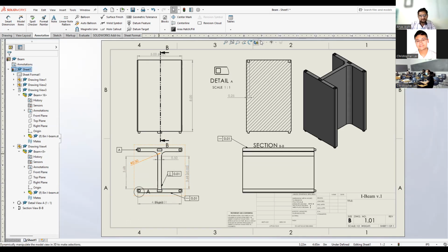Yeah, so it's pretty straightforward. Regardless of what software you're using, export your files using the STEP file function or that type of file, and then you can open that in SolidWorks or Fusion 360. I'm pretty sure you can open it in AutoCAD as well. And then after that, you can do whatever you need to do in the other software.